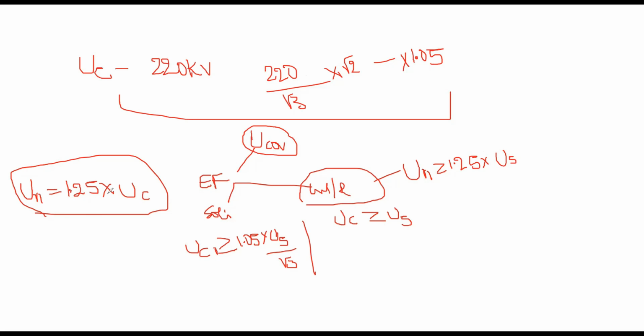The rated voltage can also be examined by a completely different approach. This is one way of approach. The other is by examining the temporary overvoltage state. Generally, for solidly earthed systems, temporary overvoltages go up to 1.4 times, considering the fault factor of 1.4. That will stay in the system from a few tens of seconds up to several seconds. So the power frequency voltage above its continuous operating voltage can only be applied to the lightning arrestor for a limited period. The higher the voltage, the shorter the permissible time.